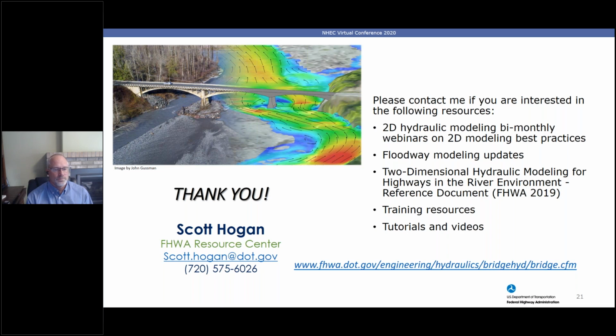Okay, next question was, how do you address negative surcharge in 2D modeling if you encounter them? Well, so far, FEMA recognized by changing conveyance and changing flow distribution that you might see a reduction in water surface. The biggest thing they're interested in is that reduction is not caused solely by an increase in velocity. And so for now, they're acknowledging that negative surcharges will be allowable in 2D model floodway analyses. But again, there's some ongoing discussion there and wondering if we need to place some other criteria along with that.